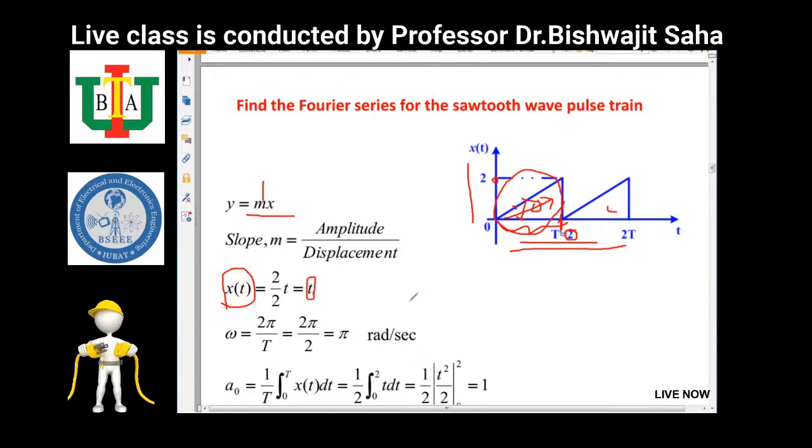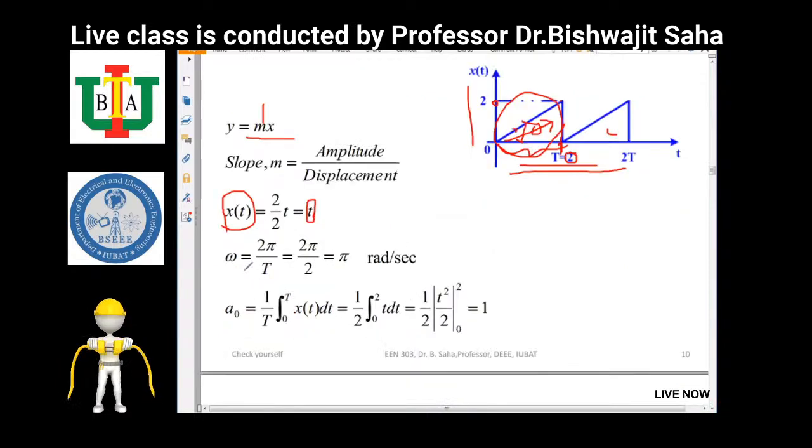It's an easy function, right? Another one is omega equals 2 pi f. However, f equals 1 over T. So 1 over T comes in with the 2 pi. The value of omega is pi, because the 2s cancel out, so pi radians per second is the angular velocity of the signal.